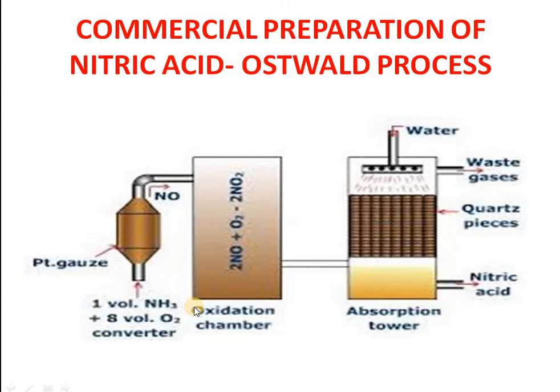These gases can be recycled back after checking the quality, meaning dust and any impurities should not be there, and then fed back into the reaction chamber. Quartz pieces help in the absorption of nitrogen dioxide gas in water. They provide more surface area and are corrosion resistant, and nitric acid is obtained in the absorption tower.